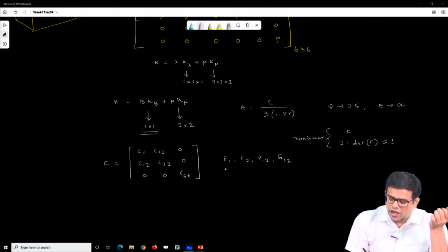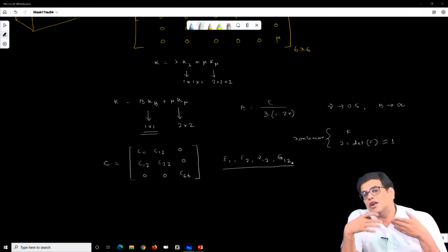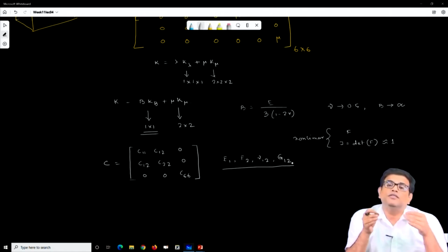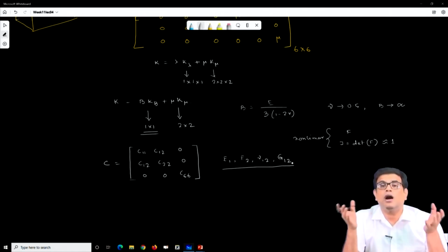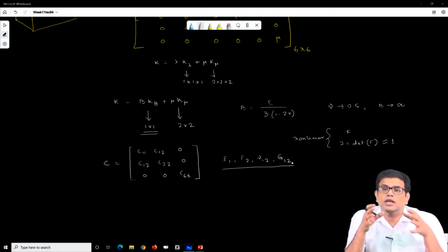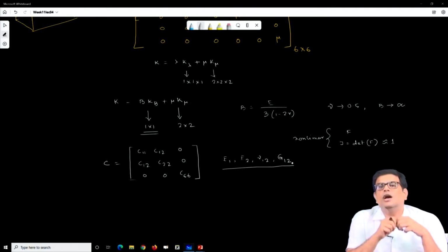So for this kind of material we cannot use it simply like this. In that case we have to use a different technique, known as the B-bar method or strain projection method, which considers the mean dilatation, or mean volumetric deformation, or mean dilatational deformation.